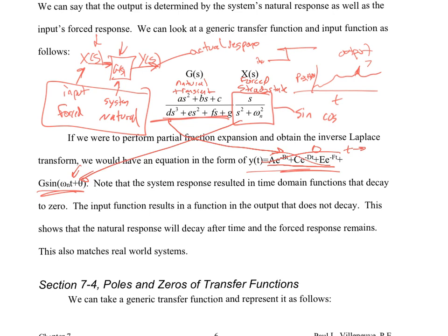Okay? So if I continue to energize a system, it's going to respond. There's only one type of system that does not. Do you remember in the case when we talked about second order systems? We have over, under, and critically damped. What if there's no damping? What if there's no resistance? Once you energize a system, an inductor and capacitor system, they're just going to keep exchanging energy back and forth, back and forth, back and forth for forever. And if there's no resistance in the system, there's no energy dissipation, which means you've energized it once, and you go away. We talked a little bit about this in the class the other day. That's how we get an oscillator, right? It's something that rings and rings forever.